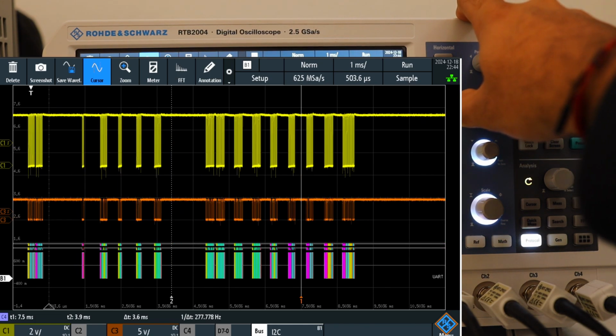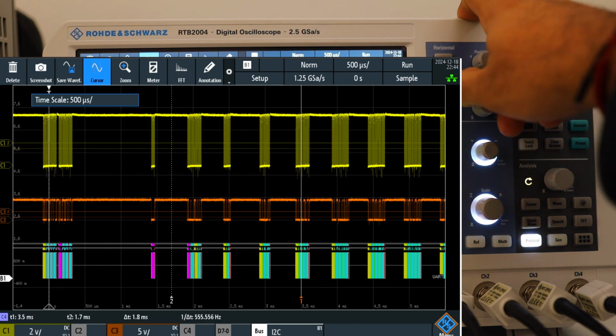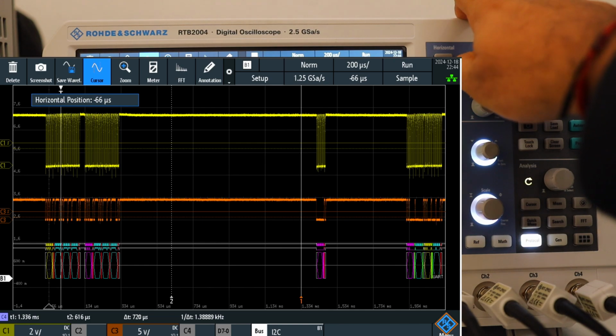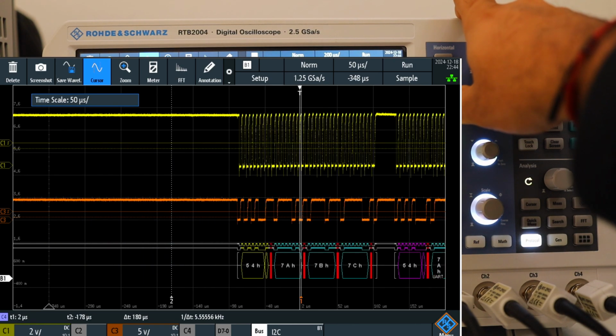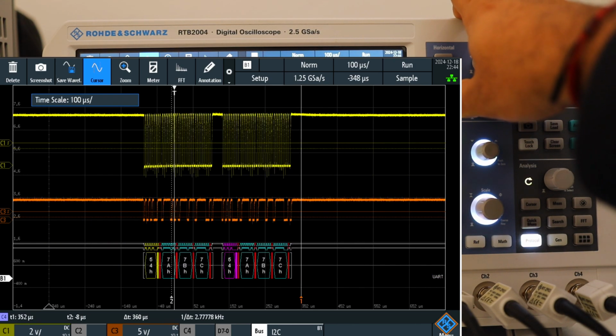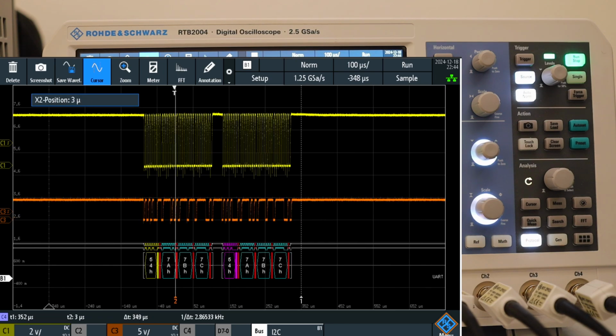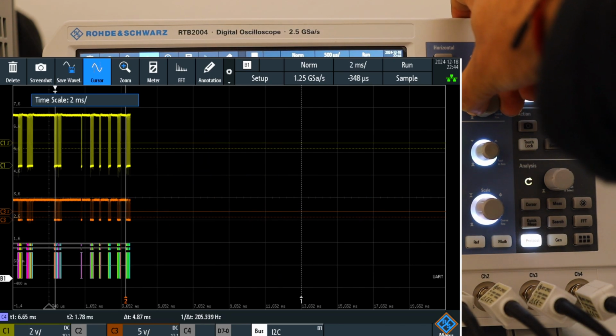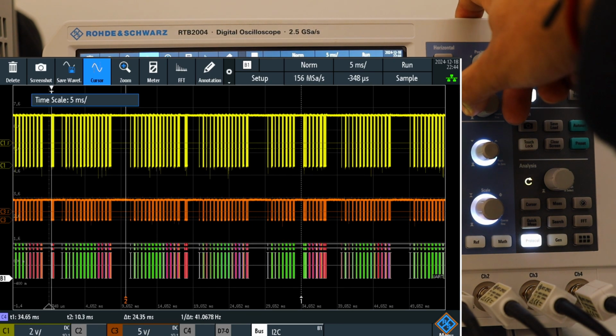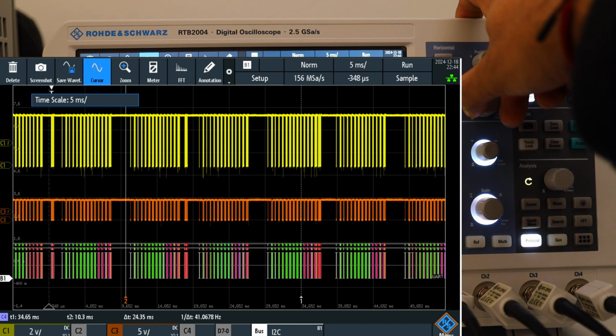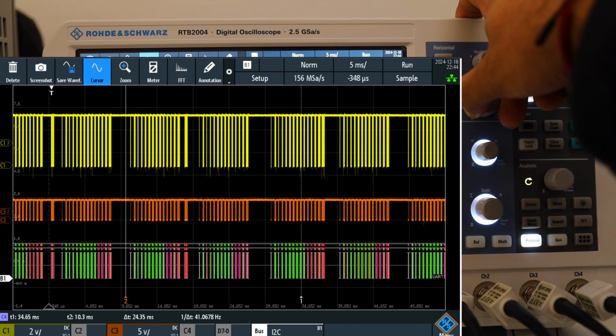So wunderbar. Now we are doing a data trigger on a specific address and specific data. Remember that packet, and this T is representing our trigger point. Exactly when it detects 547A, it triggers. And let's zoom out. Let's see if this is a stable trigger. It appears to be a stable trigger, at least more stable than the previous trigger.